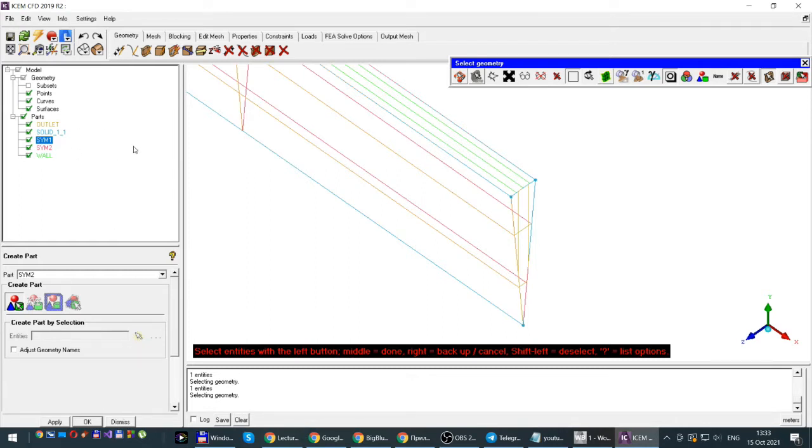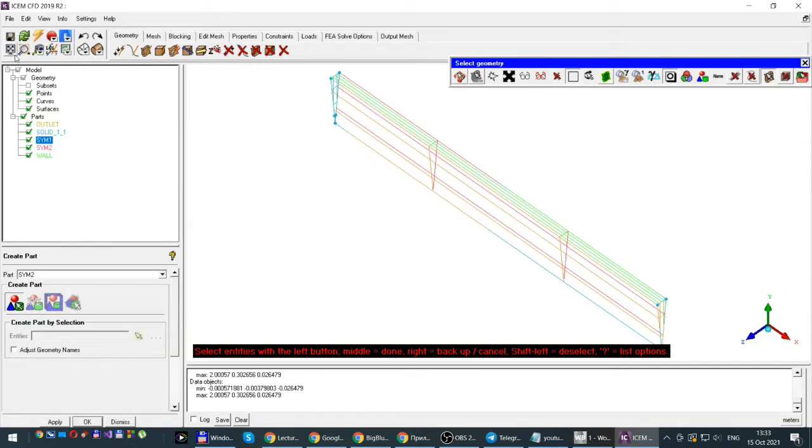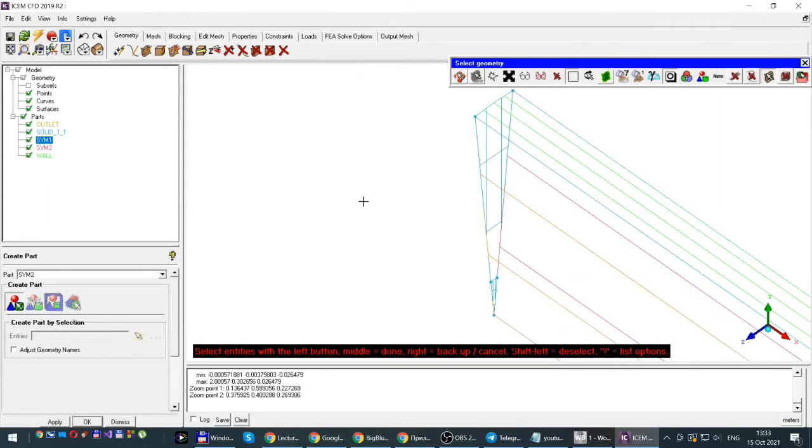Let's go to the inlet part. For this case I click Fit Window button and again use the box zoom button for the inlet part. I have two inlets, the fuel inlet and air inlet. So fuel inlet, I will write it in one word: inlet.